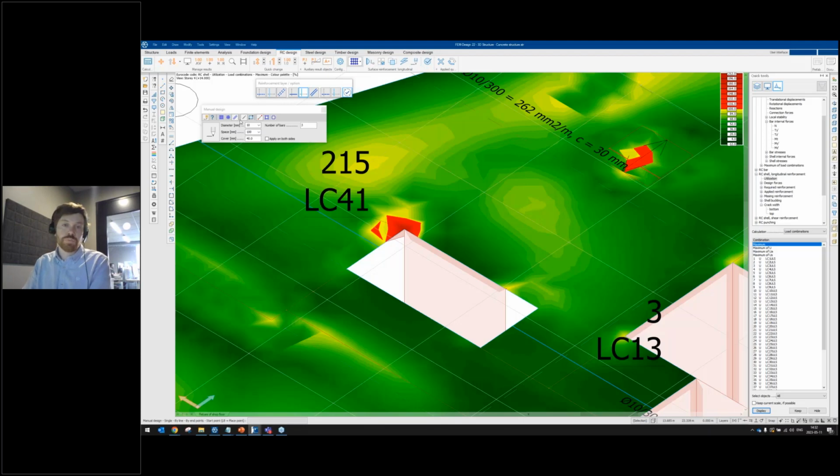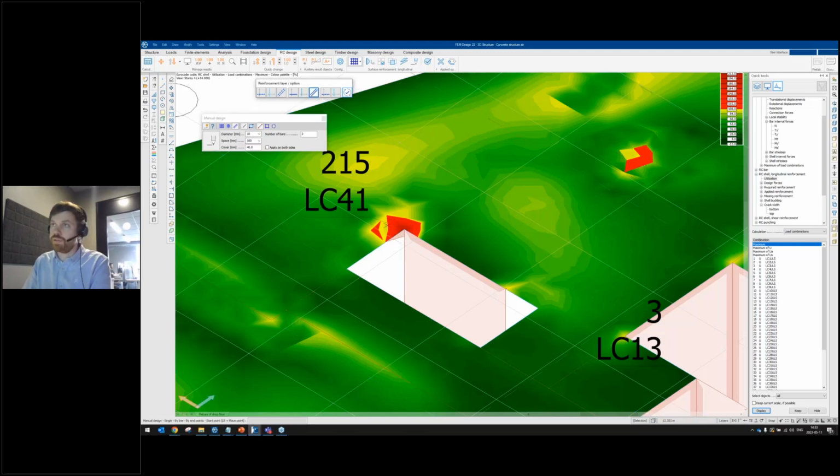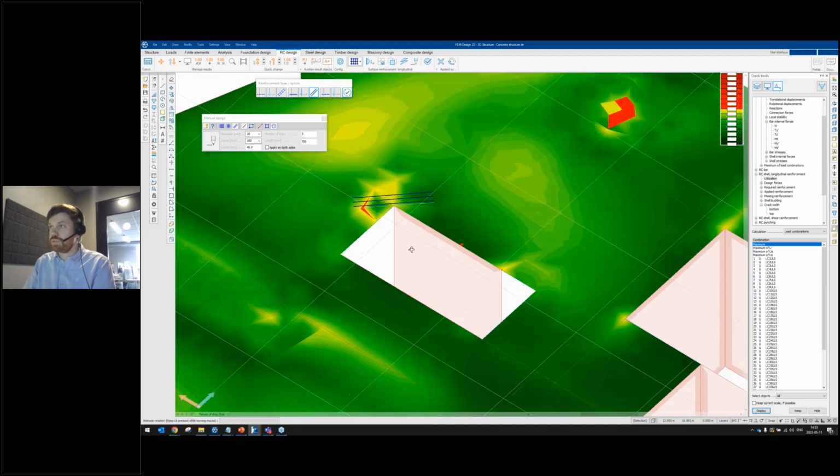And here there's a new option in FEM Design 22 where you can select single bar. And you have a new layer also called single top and bottom. So I will place myself in the top single because it was overutilized in the top. And I will apply some single bars. So you have the option to draw them by endpoints or by shell edge or shell corner. Let's start with shell corner and see how it works. So I can just select this corner and it will apply reinforcements in the corner like this.